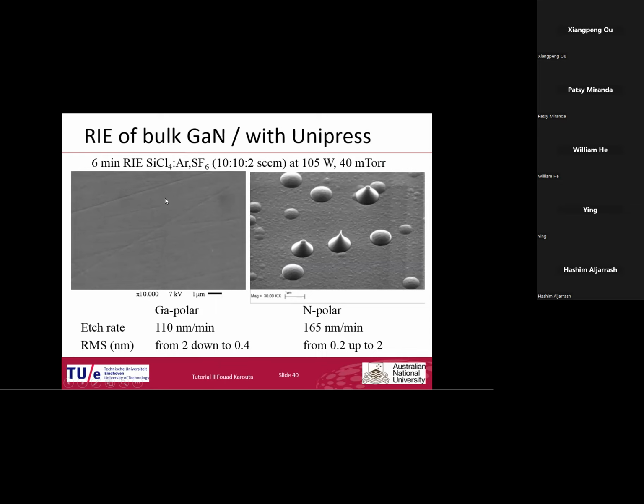These rays here are from the polishing process beforehand. So it's not induced by the reactive etching. It was induced by the mechanical polishing. And what we were trying here to achieve with this polish group is to remove the damage from the mechanical polishing, so that they can grow on it structure. And with this way, they have shown laser work in gallium nitride grown on such structure.